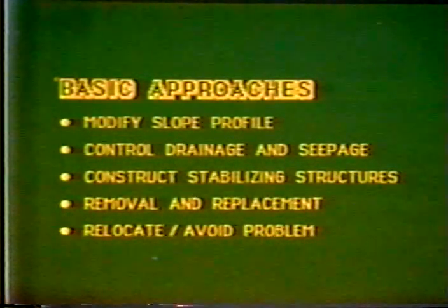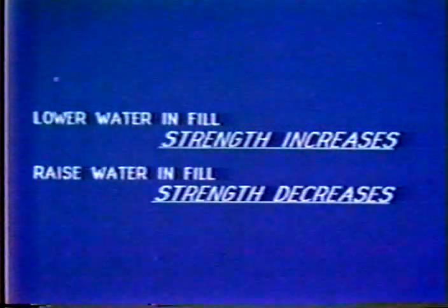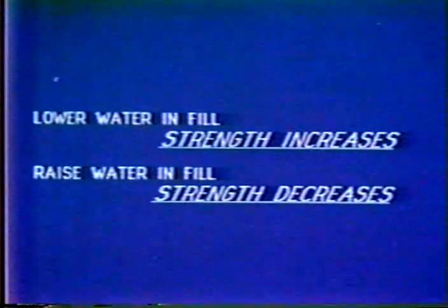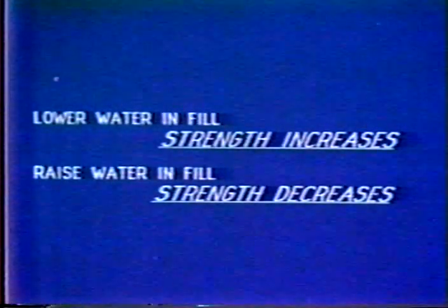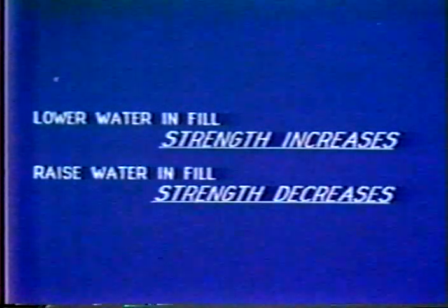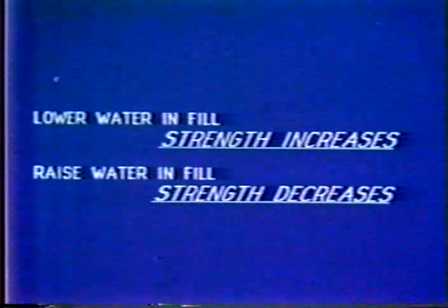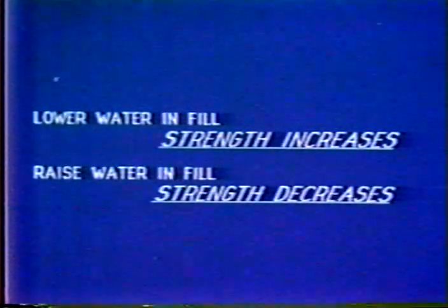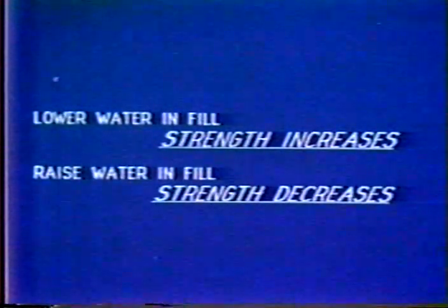But let's go right into the first method there. There's several techniques of modifying the slope, but let me make one comment back up here a minute and stress one important principle here. If we lower water in a slope, we increase the strength. If we raise it, the strength decreases. So this is an extremely important point of view for controlling subsurface and surface waters. And we've talked about surface waters earlier.